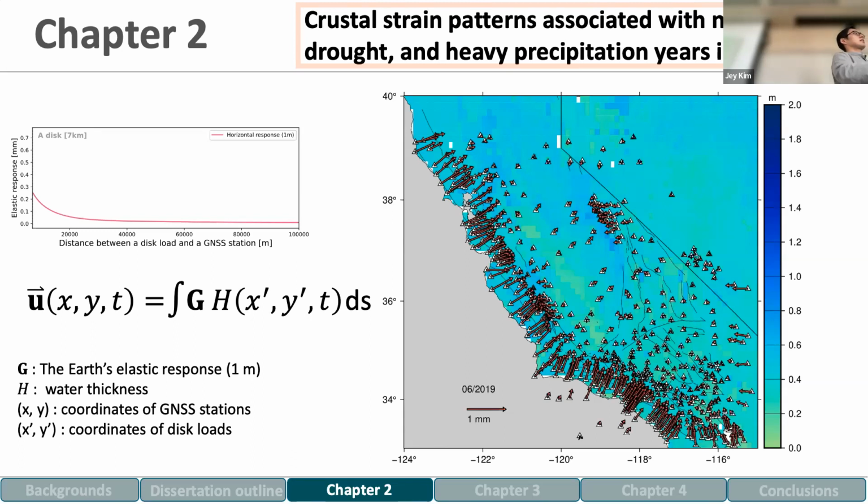But for poroelastic, when you add water and it fills up the pores, therefore you have uplift. And when you lose water, you have space, therefore maybe compaction happening, therefore subsidence. So the vertical responses are totally different. That's how I can distinguish stations affected by elastic or poroelastic. And in this case, I'm only considering elastic responses.